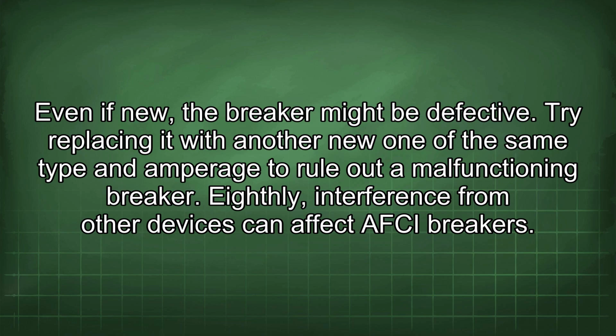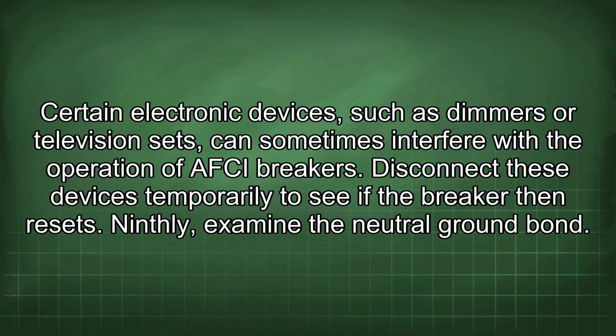Eighthly, interference from other devices can affect AFCI breakers. Certain electronic devices, such as dimmers or television sets, can sometimes interfere with the operation of AFCI breakers. Disconnect these devices temporarily to see if the breaker then resets.